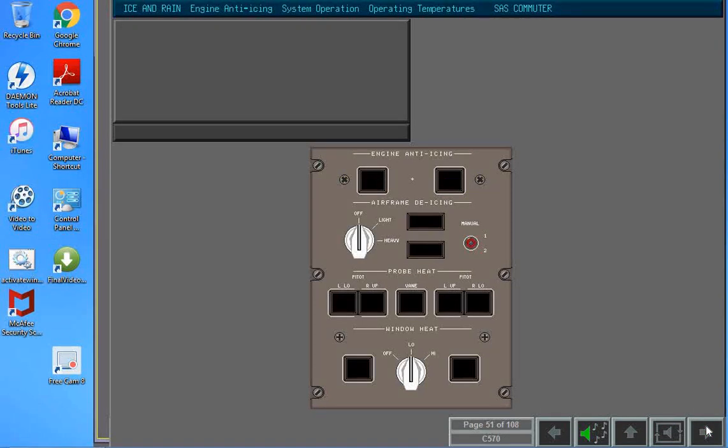Automatic operation of the anti-icing ceases if the total air temperature rises above 7 degrees Celsius, 44.6 degrees Fahrenheit, the temperature in the anti-icing control unit rises above 100 degrees Celsius, 212 degrees Fahrenheit, the propellers drop below 675 revolutions per minute, or the timer control fails. If a timer fails, all electrical heating is disabled.